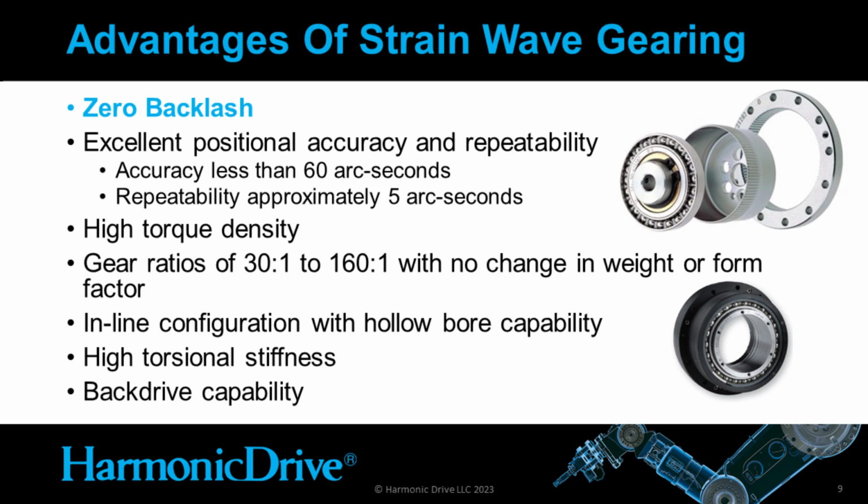All right, so now that we have a basic understanding of how the strain wave gear works, let's talk about some of the advantages, and then we'll see how this applies to actuators designed using strain wave gears. So the major advantage of a strain wave gear is it has zero backlash. This is because of its high percentage of tooth engagement that allows an interference fit around the teeth.